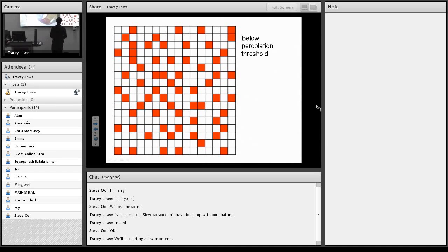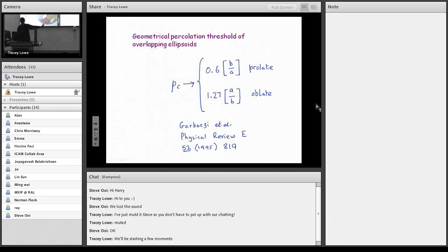So the idea was that once you lose continuity through the austenite, you're actually stressing the martensite that is formed and also the ferrite, which is also very hard. So then you get fracture. So we wanted to probe this percolation. And what better way to probe it than to introduce hydrogen and see how it behaves? This is just percolation theory, which indicated that 0.1 was about the right value of austenite needed.